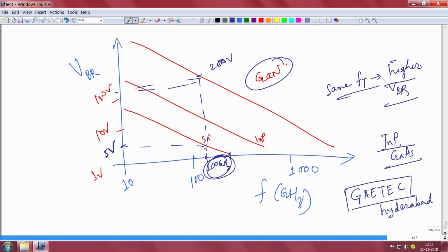It basically makes these gallium arsenide MMICs, or monolithically integrated circuits, with all the transistors in gallium arsenide, and they even work on gallium nitride. You'll see that they make these devices for strategic and other space applications. These are indigenous gallium arsenide and gallium nitride devices that are being made, and these are very important for RF applications, okay. So now there is a trade-off in RF devices, not in terms of breakdown and on-resistance but in terms of frequency. The Johnson figure of merit is also called the power-frequency trade-off, or PF squared trade-off, okay.